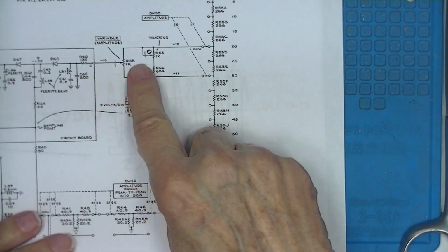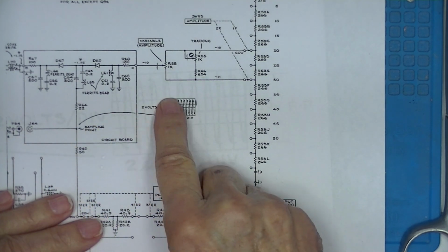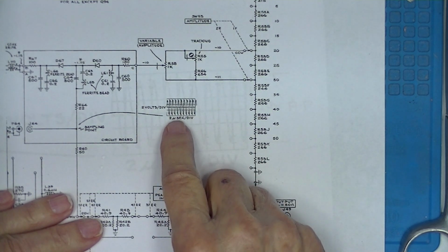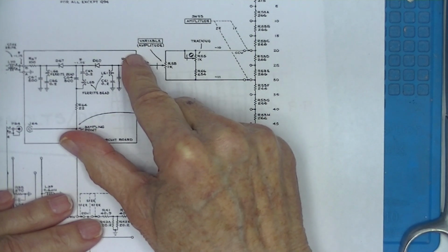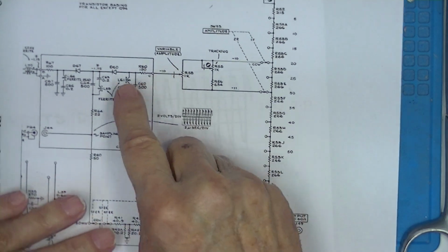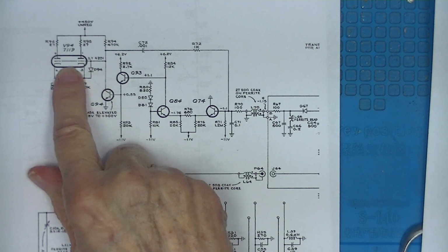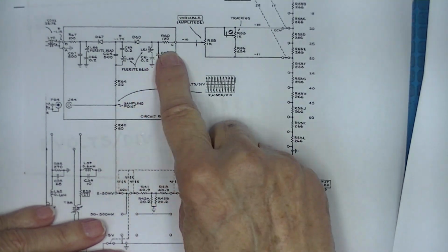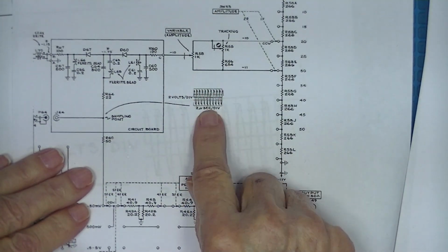When this output voltage, which is selected by this whole menagerie of stuff, is 10 volts, the oscillator output is 10 volts. If I lower this to 1 volt, this signal lowers to 1 volt peak to peak. It's a peak-to-peak detector and comparator. It detects the peak-to-peak voltage from the oscillator, compares it with this, outputs a difference signal, which is varied by these gain stages, which varies this variable resistor setup in order to make this peak-to-peak rectified voltage equal to that. So 10 volts here, minus 10 volts actually, provides a 10 volt peak-to-peak signal.